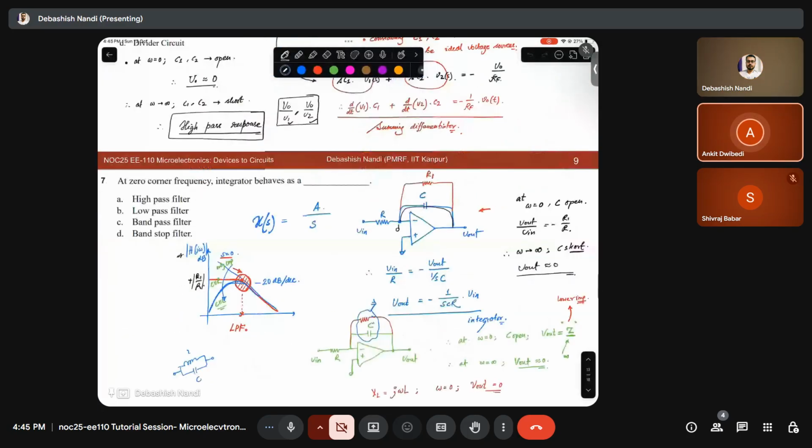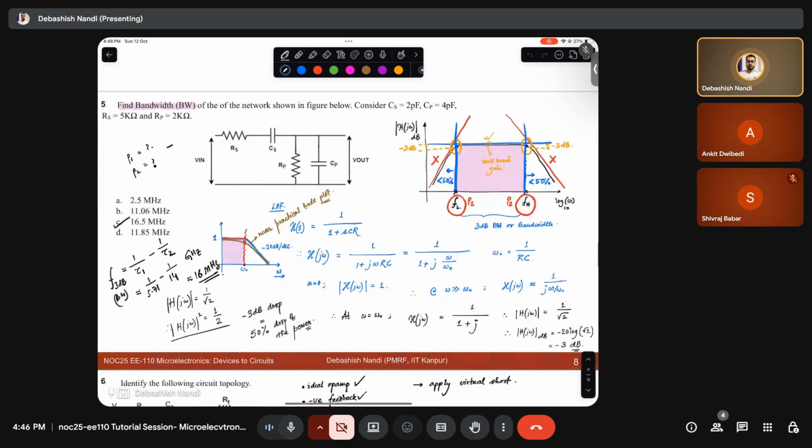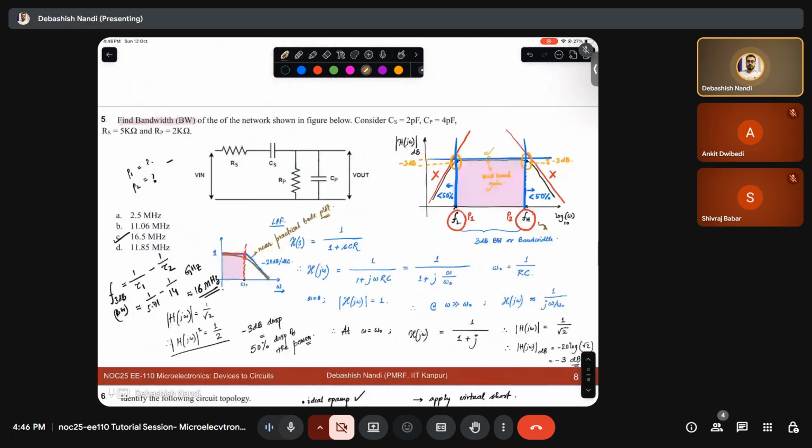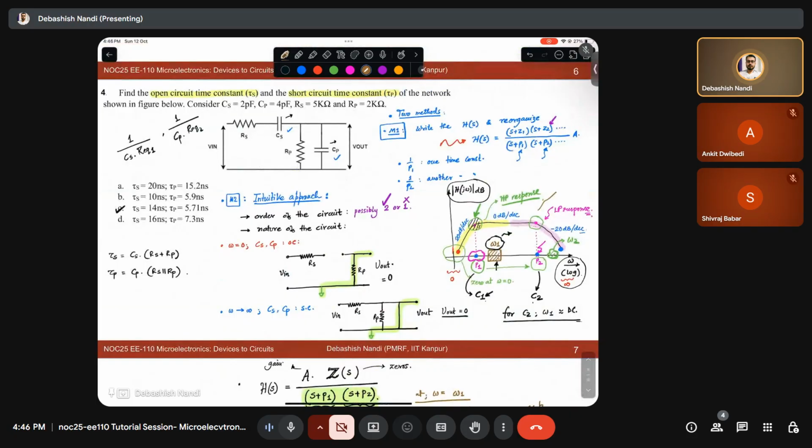It is in the prior week document, I guess. So it is the same thing, right? We have covered this in the last session. In the last session, we mentioned how your FH will come about. It has nothing to do with your transistor for that matter, because you can break down your transistor to a small signal circuit. That will be nothing but your impedances, currents, control current sources and capacitances. So this FH comes the same way that you calculate your open circuit and short circuit poles, right? This we have done. So that is why I have not shown it this time. I thought that it was covered.